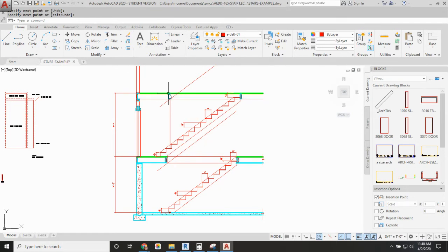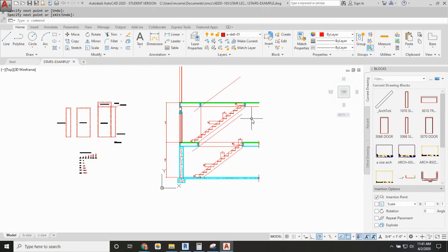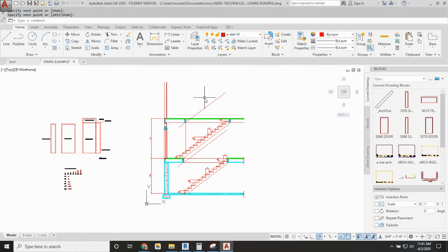And so up here we could have a closet on that second floor in one of the bedrooms. So we might come up in the center of the room like a cape. If you think about a cape or a colonial, the stairs are centrally located. And then you go to a bedroom on either side maybe, and one of them anyway could have a closet, or you could split that closet in half if these stairs are wide enough. Let's say the stairs are 4 feet 6 inches, then each closet could be about 2 feet deep. And you could have half, closet in one room and closet in the other.